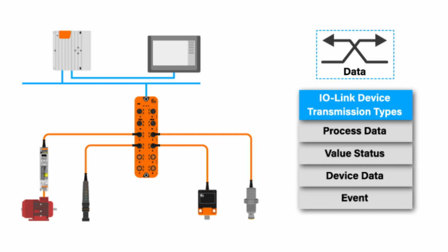So let's summarize what we've learned. IO-Link is a simple communications protocol. It is used primarily for communications to simple 3-wire sensors and actuators. An IO-Link master has slave devices such as an actuator or sensors attached to it. The IO-Link master can then communicate over a field bus connection to the higher level controller, most likely in our case, a PLC or programmable logic controller. The IO-Link ports can serve different purposes, from signaling that is unused to signaling that is in input or output mode, or for IO-Link communication.